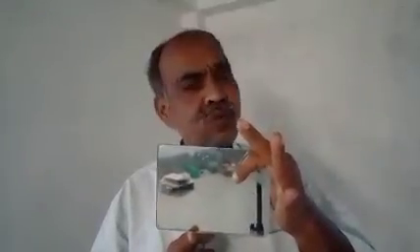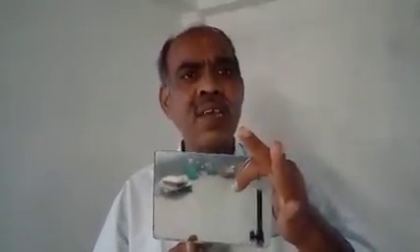So somewhere here is that point, along this length. But point A was where? Point A was here. So we need to know the distance from this point A up to this centroid. What will be the distance? It will be L minus L by 3, that is 2/3 of L.